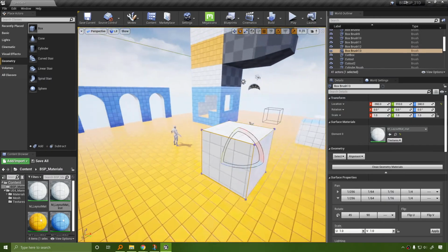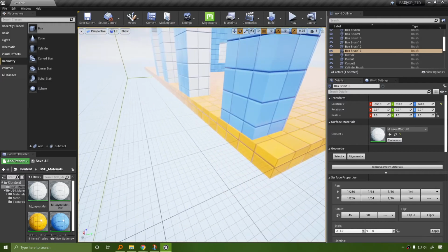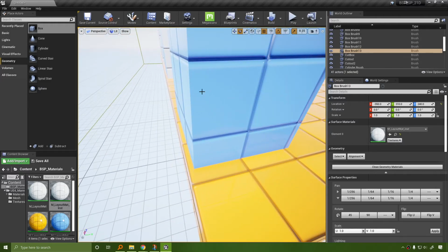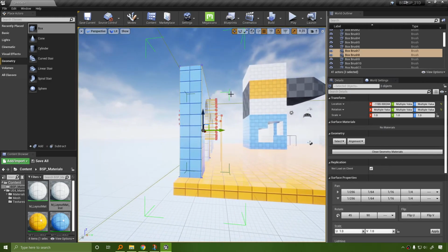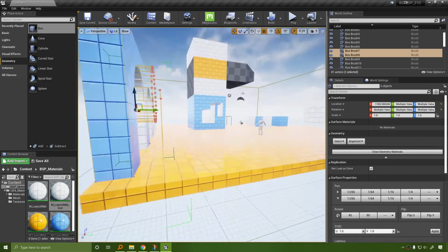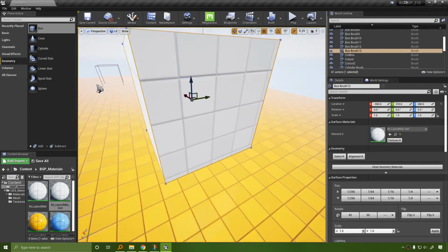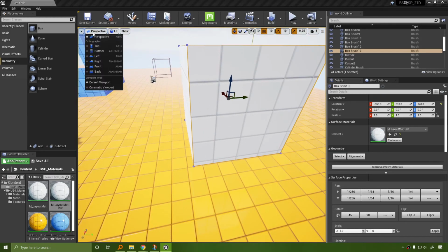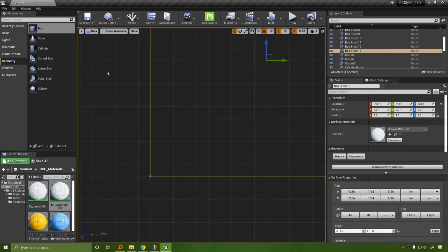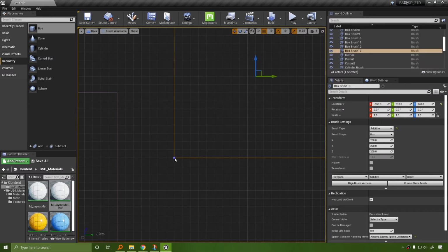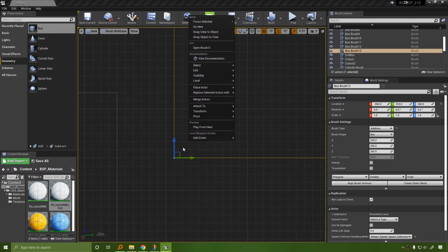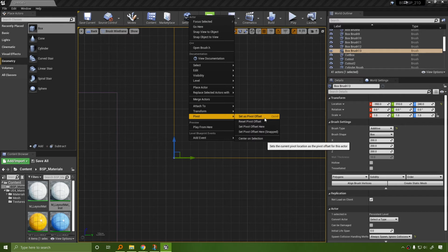So if I'm going to be making something like this so that I know it always snaps correctly to the right location, as you can see, this is not snapping because our center point is set in the middle of the object, and any slightly miscalculated rotations are not going to work. We need to set our pivot correctly. So in order to set our pivot, it's easiest to go to the correct perspective. Make sure you select the face. Right-click the vertex that you want to assign so that your object is selected. Right-click the background, go to pivot, and then set as pivot offset.